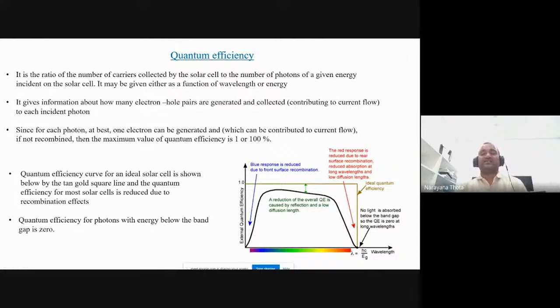That is, recombination losses, voltage losses, and optical losses will be there. Because of these losses, this is the actual curve. So this is the cutoff wavelength for efficiency. If the wavelength is too high, the light can pass through the solar cell, and if it is too low, it is unable to generate electron hole pairs. So these are the cutoff wavelengths.